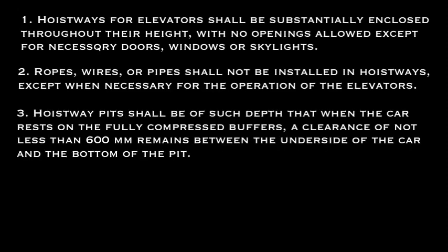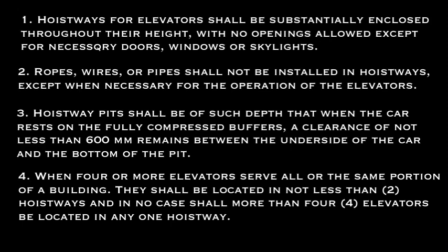Hoistway pits shall be of such depth that when the car rests on the fully compressed buffers, a clearance of not less than 600 millimeters remains between the underside of the car and the bottom of the pit. When 4 or more elevators serve all or the same portion of a building, they shall be located in not less than 2 hoistways, and in no case shall more than 4 elevators be located in any one hoistway.